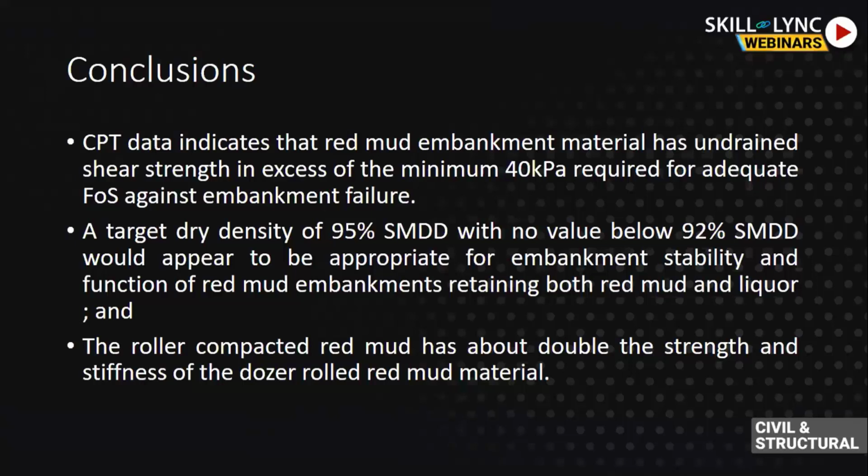If the soil is moldable and breaks into only a couple of pieces when dropped, it has the right amount of moisture for proper compaction. If the soil is plastic in your hand, leaves small traces of moisture on your finger, and stays in one piece when dropped, it has too much moisture for compaction.